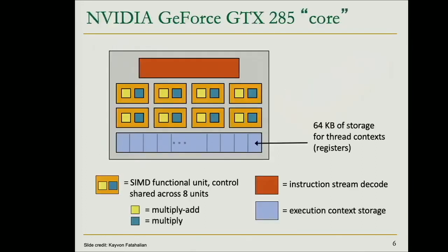You can see the detail here. This is one of these cores, one of these streaming multiprocessors in NVIDIA terminology, and inside each of these we have these different lanes. You can see the 8 of them. Inside each of them we might have several processing elements or several ALUs. For example, we have something that is able to do multiply accumulate operations, or multiply add operations, that are very useful for linear algebra, for neural networks, for example. And we may also have other ones.